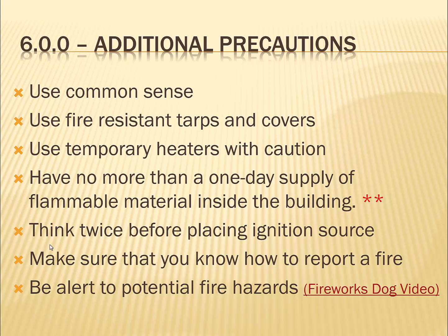Okay, so there's common sense in fire prevention. You use fire-resistant tarps and covers if you have to protect. You use temporary heaters very carefully. You should have no more than 1 day's supply of flammable material inside the building. So that's one rule. The OSHA somewhere else defines that as no more than 5 gallons of gasoline, or no more than 10 pounds of propane.